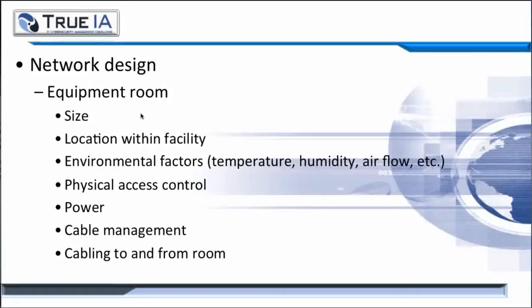How are you going to manage physical access control? Are you going to have a combination on the door, or will there be a prox reader? Well, that's going to take consideration before you start installing equipment. It's a lot harder to do these things after the fact. What are your power consumption requirements? Remember, data centers, again, use a lot of power. Do you have enough clean power being provided to the facility to allow uninterrupted service to the organization? If not, you may need to consider a line conditioner or UPS backups.